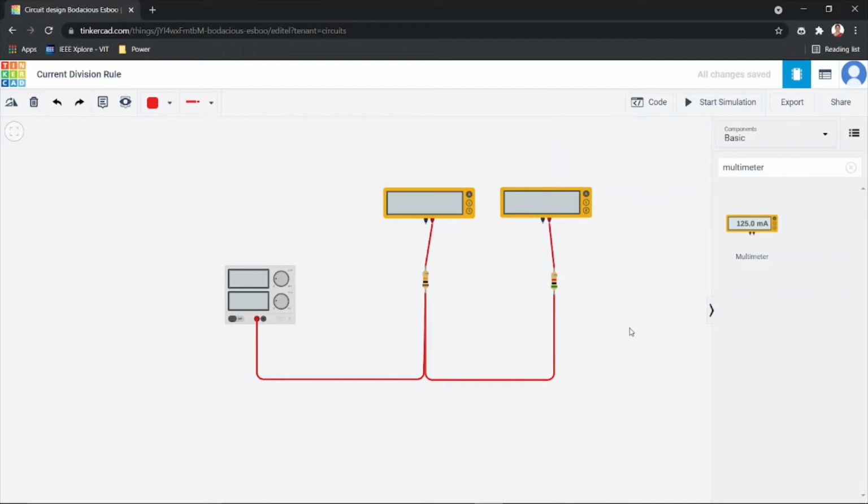And then we need to connect all the ground connections here. For the ground, we usually use black color. So I've just selected that. Click on this and then join the black colors, the negative terminals of your multimeters. So this has to be again connected to your other negative terminal. So all the negatives are connected now. So now everything is over.